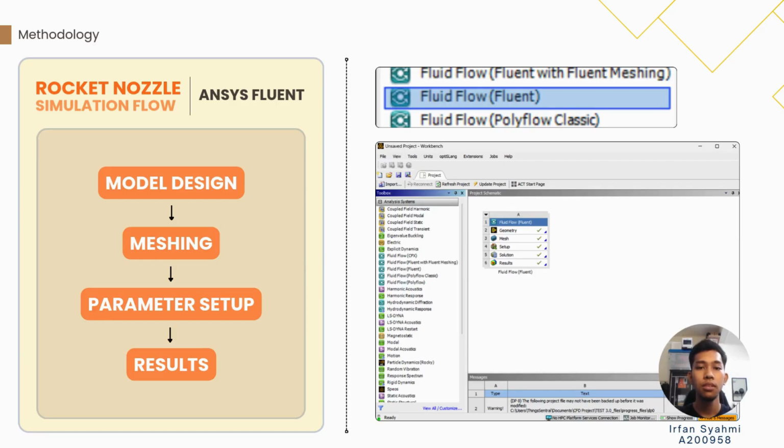Running a full 3D simulation of a rocket engine requires too much computing power. So, to make our study possible with our computer hardware, we simplify the complex 3D engine into a 2D flat model. It really lowers the computer workload, but still keeps our pressure data highly accurate. Using these models allows us to easily test our variables, like different nozzle size and length, to see exactly how they affect the exhaust speed. Next, I will explain the design dimensions for this model.